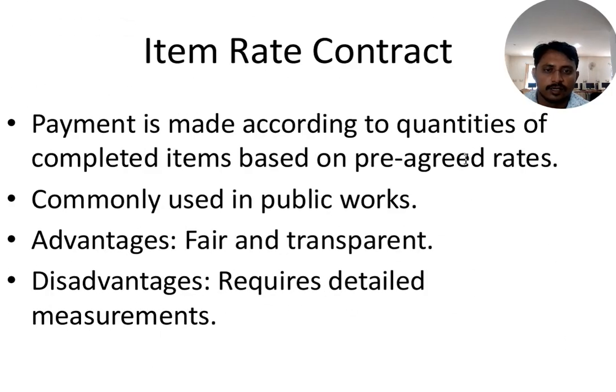The item rate contract, we already discussed. Payment is made according to the quantities of completed items. It is item based, related to item based elements. It is commonly used in the public works department and other government works, so it is suitable there. The advantages are that it is fair and transparent, and the disadvantage is that detailed measurements are required, for each item of work.